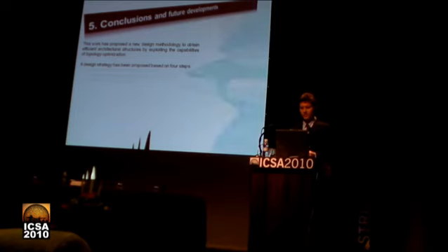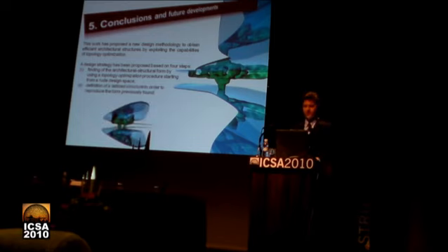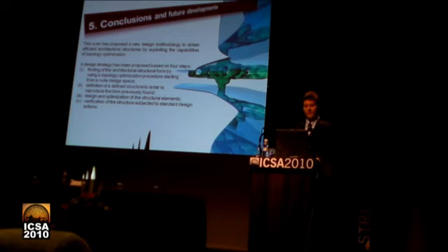In the picture you can see some renderings for a challenge in Germany to present this project. So the strategy is based on 4 steps: the finding of the architectural structural form by using a topology optimization procedure, the definition of the latticed structure in order to reproduce the form previously found, the design optimization of the structural elements, and the verification of the structure subjected to standard design action.